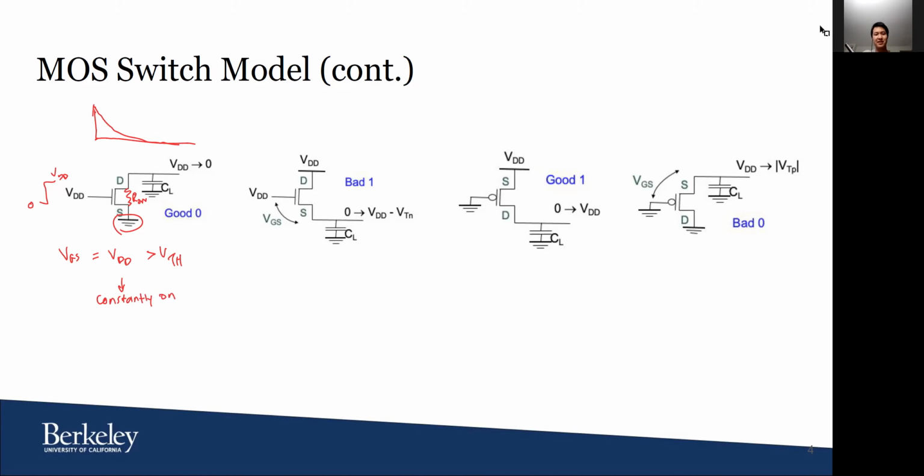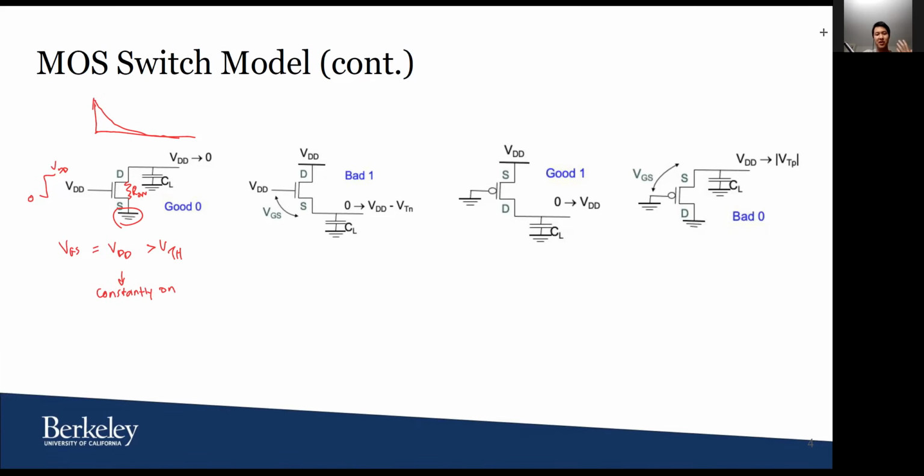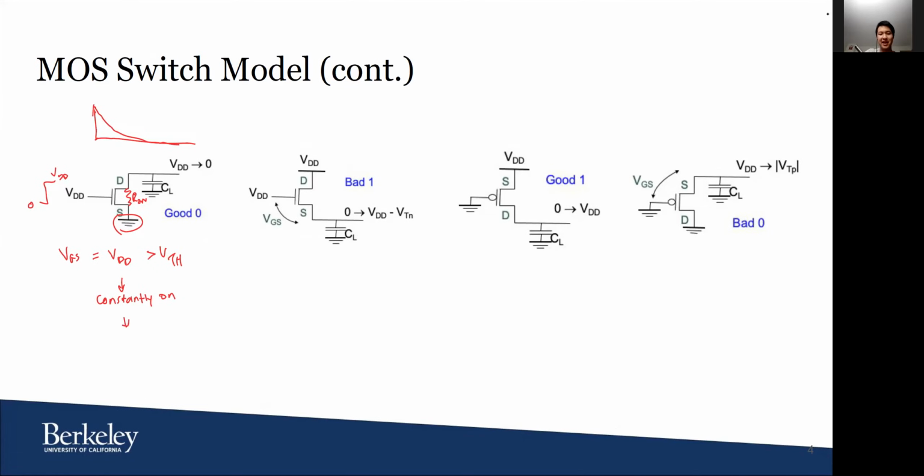And it also has the same resistance all the time. So this means that the output is going to be pulled to 0 eventually, until the output capacitor is completely discharged and the drain to source voltage becomes 0. At that time, it is indistinguishable which way the current would flow, because neither the drain nor the source voltage is different from each other.